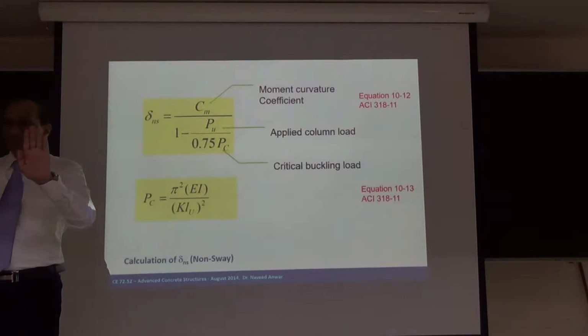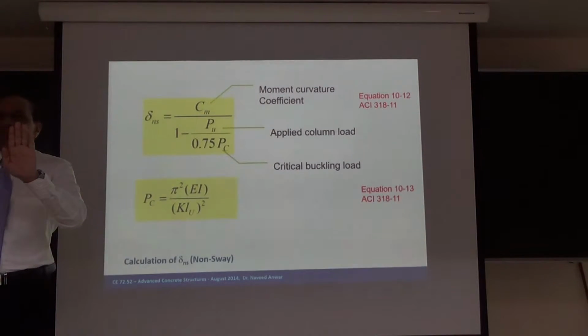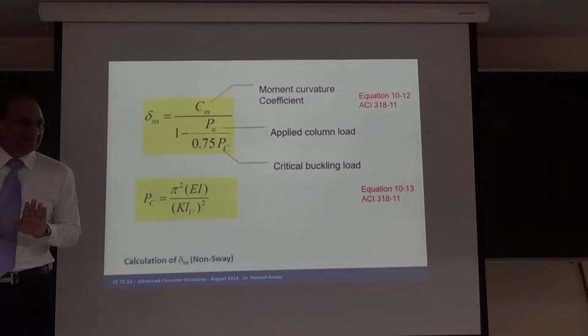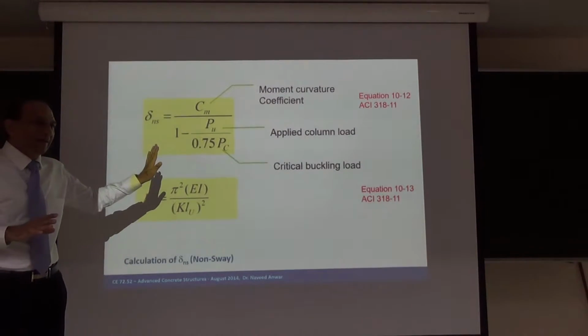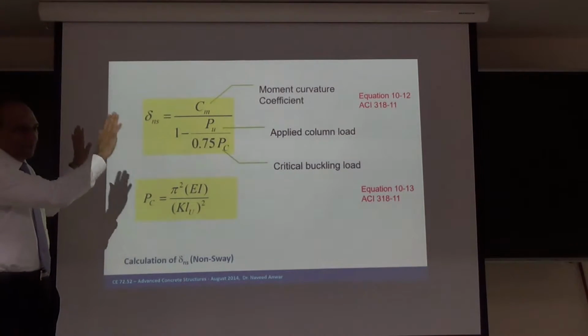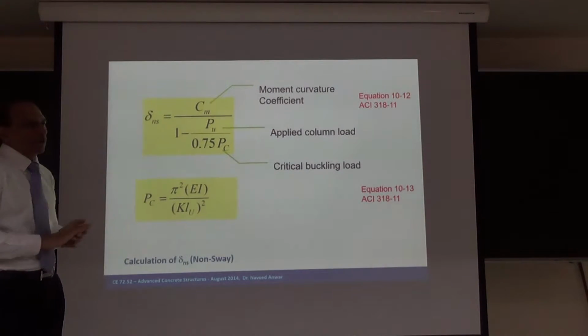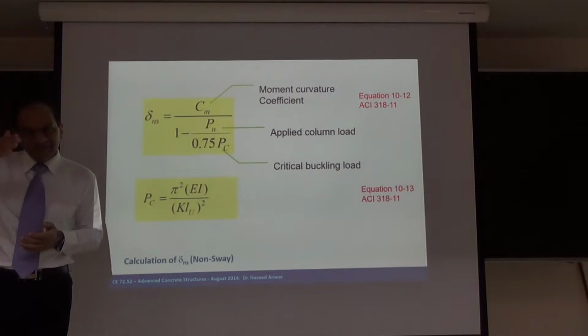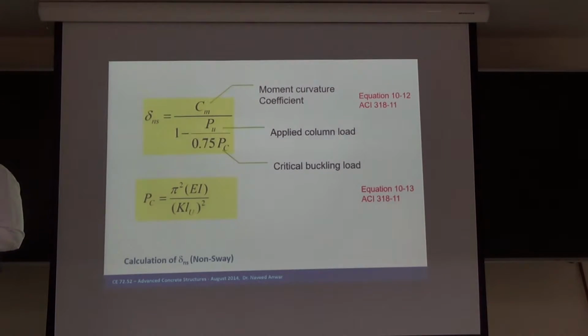And PU corresponding to the moment that you are considering, because this is a non-sway case multiplied by the non-sway moment. So it must correspond to the same load which is for that load combination. So there are some fine points when you apply these equations, which PU to take. So one load combination must be taken, a combination that is not causing sway.